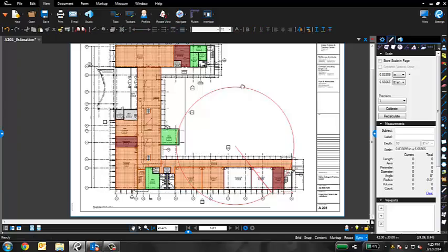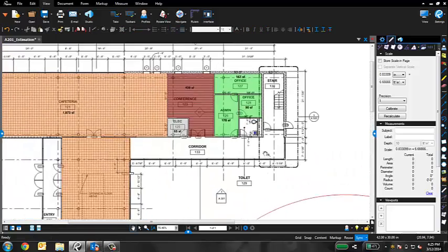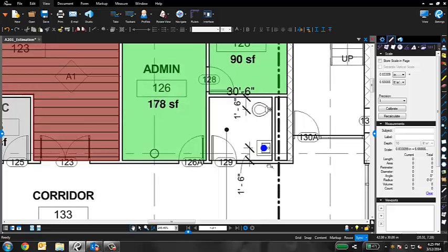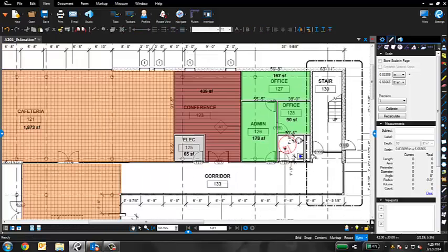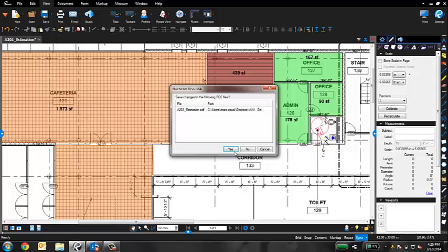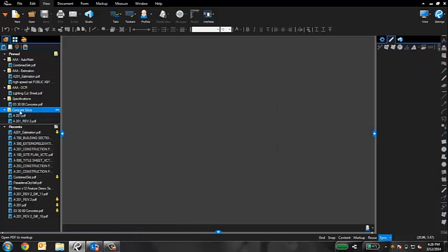Another use for this center out radius is looking at the radius in an area in, say, an ADA compliant bathroom. So with this, we can go ahead and check the amount of space available and make sure that that bathroom is 100% ADA compliant. Now, those are just a couple of the measurement tools that we've added. One of the most exciting measurement tools that we've added is the ability to calibrate both X and Y axes, however you say that.